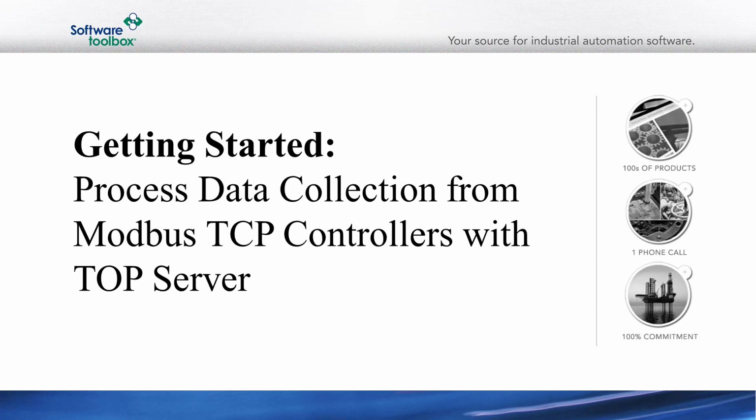In this video, I will walk through the configuration settings required for a connection to a Modbus controller using the TopServer Modbus TCP Ethernet driver. This driver implements both client and server capabilities in the same driver, allowing communication with both server devices such as PLCs, RTUs, or other control and field devices, and client devices or systems such as HMIs, SCADAs, DCS, or PLCs.